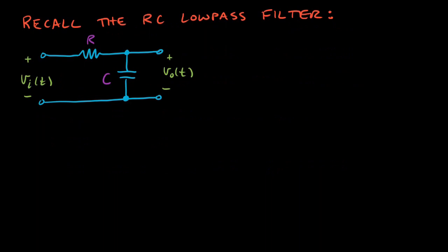To dig into this discussion, let's recall the simple RC low-pass filter that we've looked at a number of times. It's a good candidate circuit that can be used to make these points without overwhelming us with complexity. The differential equation is v_out-dot plus 1/(RC) times v_out equals 1/(RC) times v_in(t). That's a nice, simple first order linear ordinary differential equation with constant coefficients.